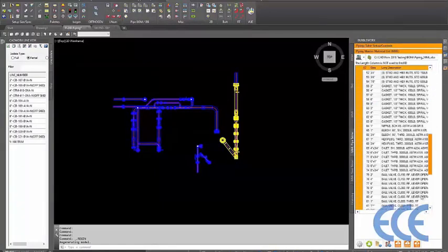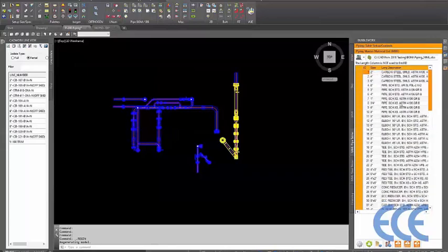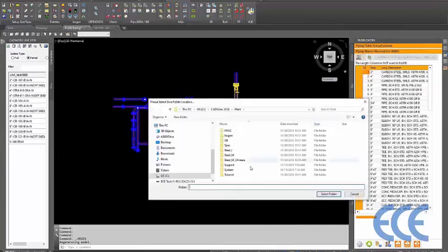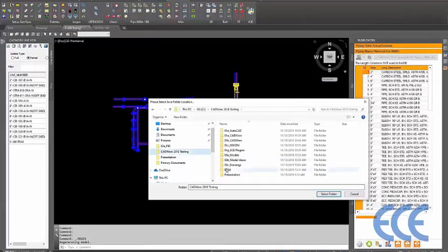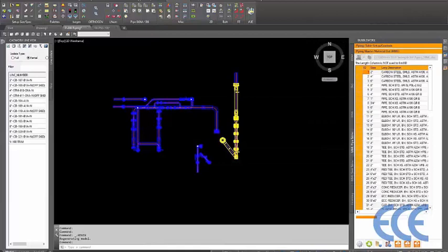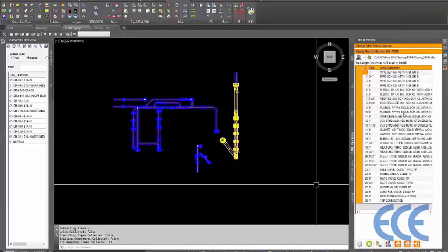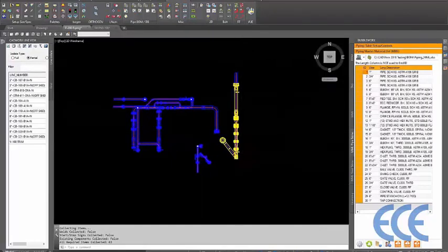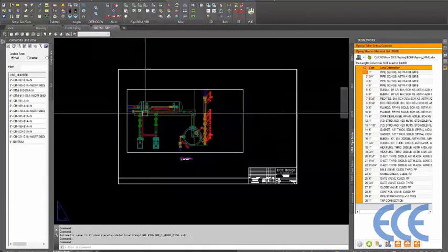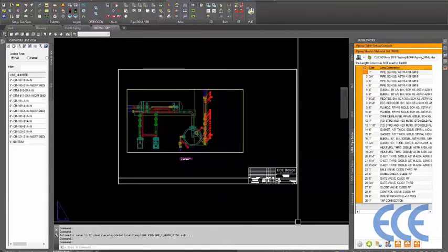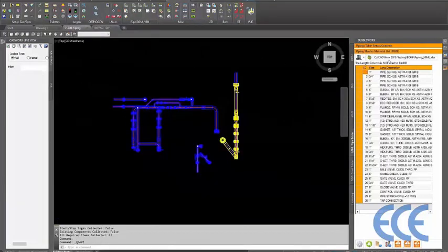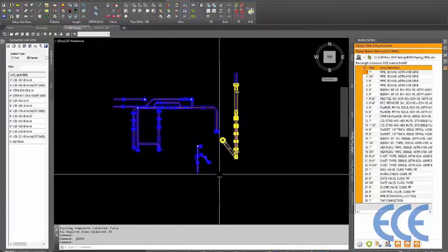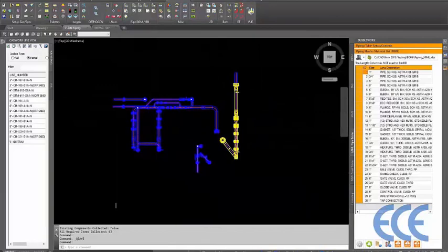And what I also want you to take a look at is the length of this list. You'll see the MML shrink, so you know that we have a new master material list being generated here. Let's go ahead and create. Let's go back to our BOM folder and select folder, and we'll run that. And you see this list got a lot shorter, right? We went from 80 items down to 30. So now we know we just have these components in. Let's go ahead and save that. Let's go back over to our drawing. And again, the big thing with this was creating a new master material list with just the components that were not on an existing layer.